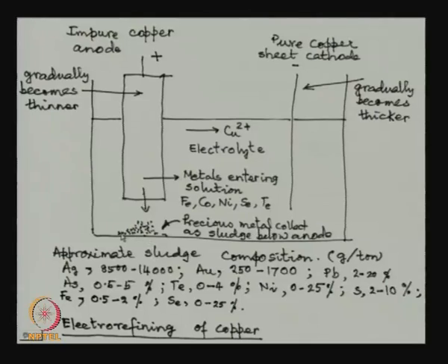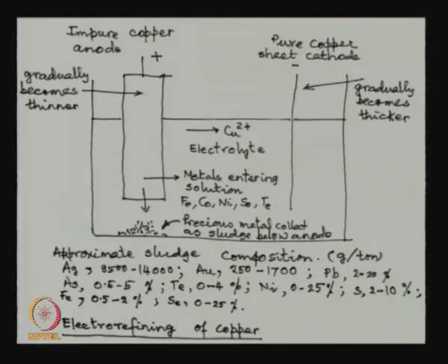Below the anode there will be some insolubles which we call a sludge, and it contains all the precious metals. All the precious metals that were in the original concentrate will come all through, because they will always be in the copper sulphide, and end up in the copper finally, and only here will they get separated, because other impurities can dissolve. Copper will go through electrolytic refining to the other electrode.